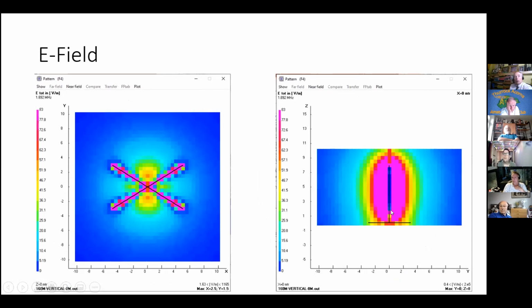And looking at the vertical pattern electric field, it's slightly different because this is a truncated antenna. This is 8 meters tall. A quarter wave on top band would be 40 meters. So you're only seeing effectively the 20% nearest the end. So you have a big E field even at ground level. And that basically, if there was anyone else around, it would need a fence around it about 2 meters out, discounting the radials, of course.